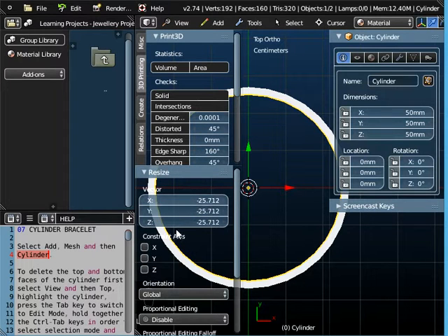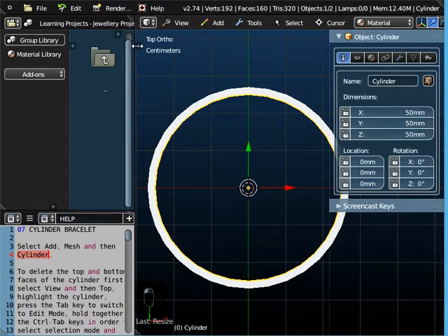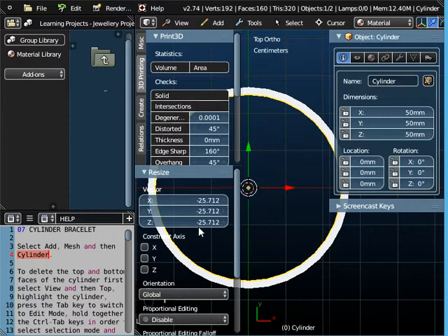Now whenever you scale in FluidDesigner, you're always going to end up changing these vector values here, the scale factor, in the toolbox window. So I opened up this window by clicking on the plus sign at the top, or alternatively I can press T on the keyboard. These values must always be at 1. Whenever there's a value for X, Y and Z there isn't 1, you must reset the scale.